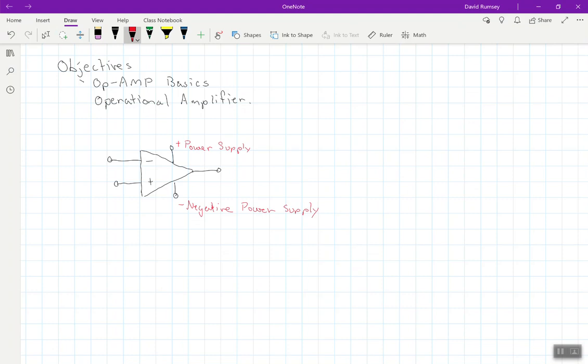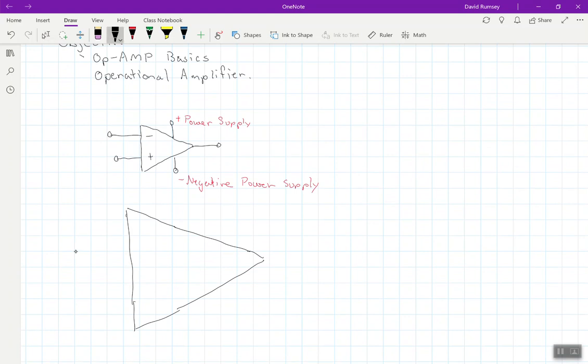So the way this op-amp works is, we've got the positive power supply and negative power supply. I'm going to redraw it slightly bigger here, and put in some circuit elements to show what's going on inside. We have our negative input and our positive input. And then we have a resistor here inside. So what we're doing is modeling. This is a model for that complicated circuit. And we label the voltage here plus minus VD, which is referred to as the difference voltage.